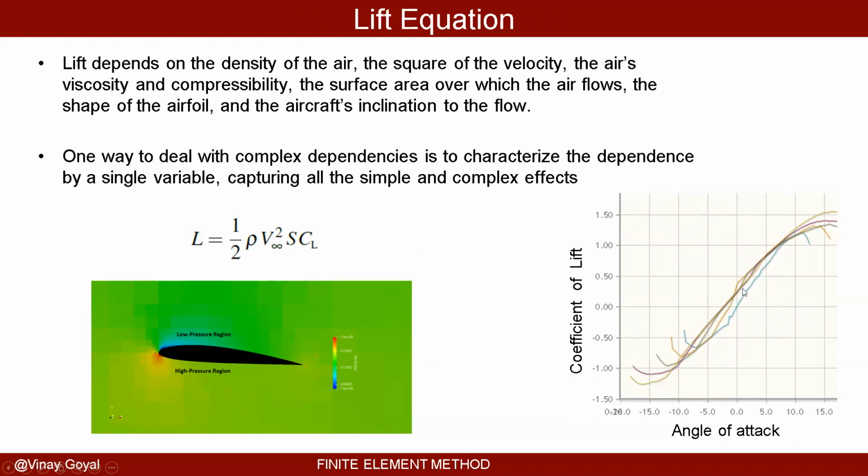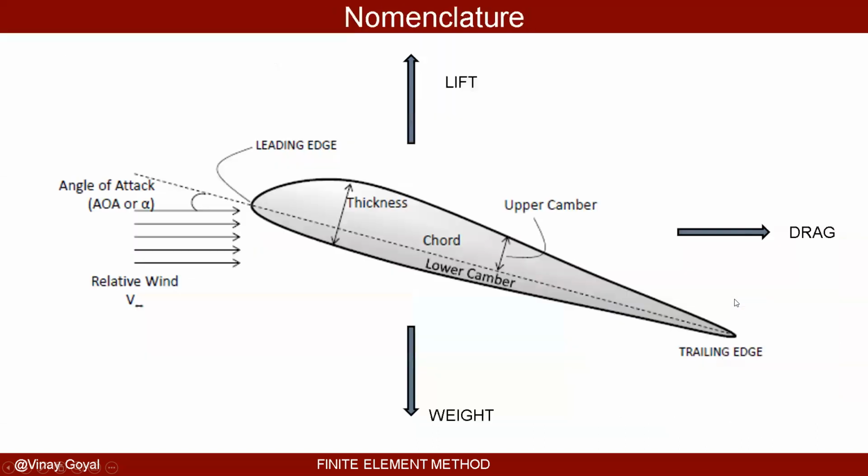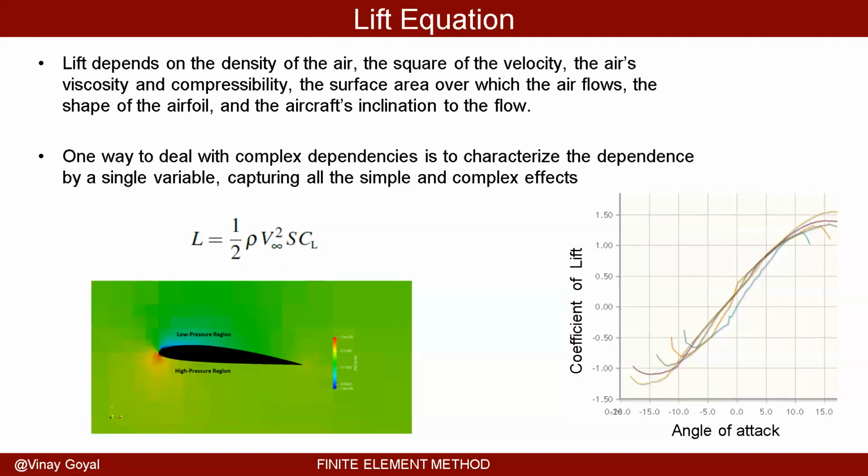As you can see, the angle of attack increases from 0 degrees. So I'm looking at this angle here. So this angle of attack 0 degrees, now this camber is aligned with the relative wind. In those cases, the lift coefficient is smaller. But as you increase the angle of attack, the lift coefficient increases until it drops off because you have too much of an angle, to the point that you have flow detachment, and you no longer can sustain or produce lift. You can see here a high pressure environment here.